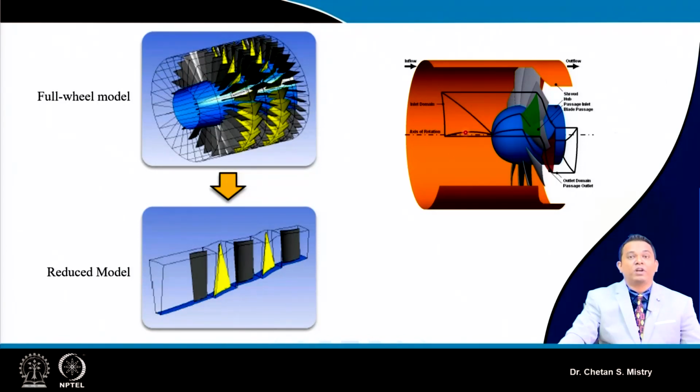Okay. Now once we are ready with our blade, when we are doing our CFD analysis, that blade we need to consider as a hollow portion, and the remaining portion, which is of our interest, will be solid. So just understand one thing here: this blade we are talking of is a hollow passage, and the remaining flow domain will be a solid passage, and that we will be dividing into a number of elements. So let's try to look at what we need to do here in terms of discretization.